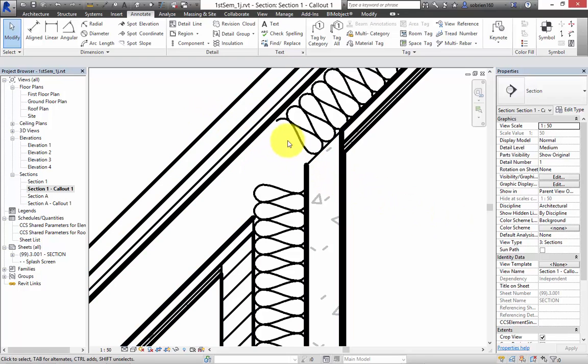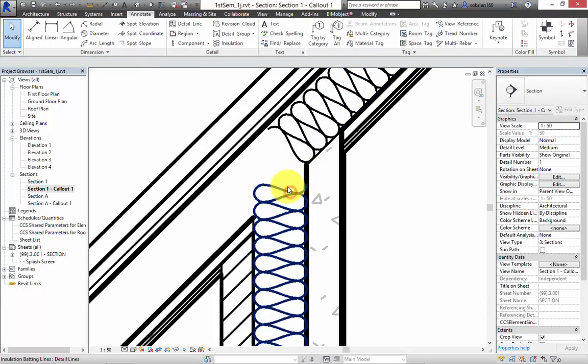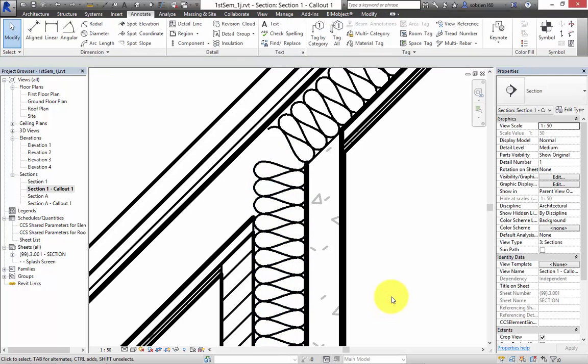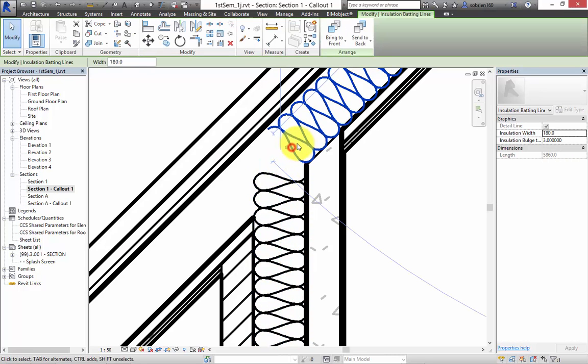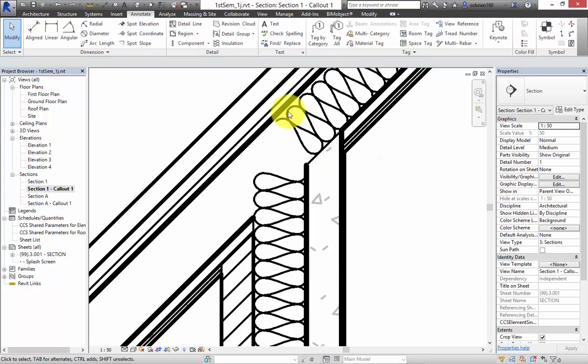So you can't just say, okay, Revit only lets us draw a straight line, therefore I'm just going to draw my insulation like that, because to anybody who's used to looking at drawings, it looks unprofessional and unfinished, and it's kind of leaving room for error. So what I generally advise people to do is to actually individually draw in the little curves afterwards to join the two of them together.